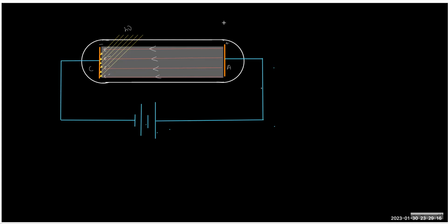It's clear what is happening? Yes, sir. So what is saturation current? It is a condition in which the charge density between the plates becomes constant. Therefore, the total number of charges leaving the cathode is equal to the total number of charges received at the anode. And this process happens without any delay. It means an electron will come out and will be absorbed on the other end almost instantly. Is this clear, what I'm saying?